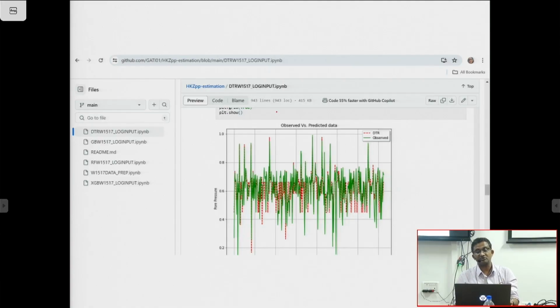Now there is a concept called autoregressive models with this log. We can have different delays or different times for how our pore pressures can be predicted. With different lags, let us say you want to predict pore pressure in 1 step, 2 steps, 3 steps, or any number of steps. It is a multi-step pore pressure prediction model, meaning it takes the information of the previous states. Now the question here is to what extent we can go back to predict the future. That needs to be fixed during the pre-processing stage of the model development.